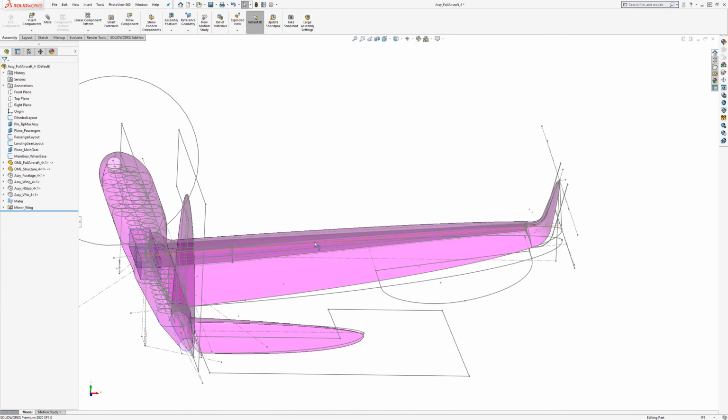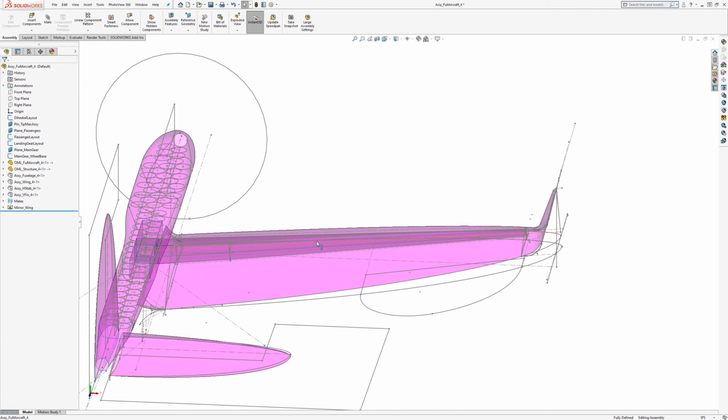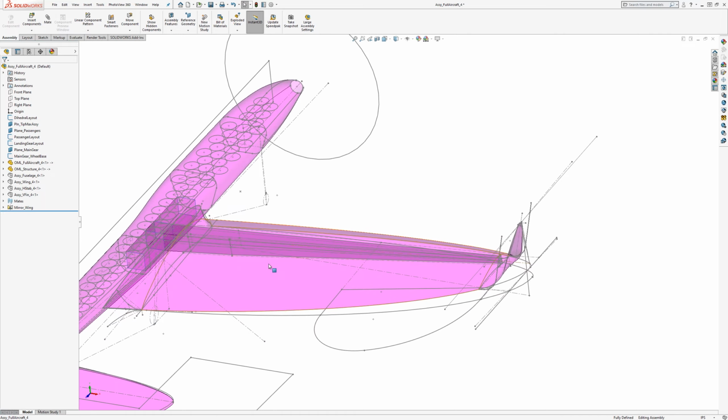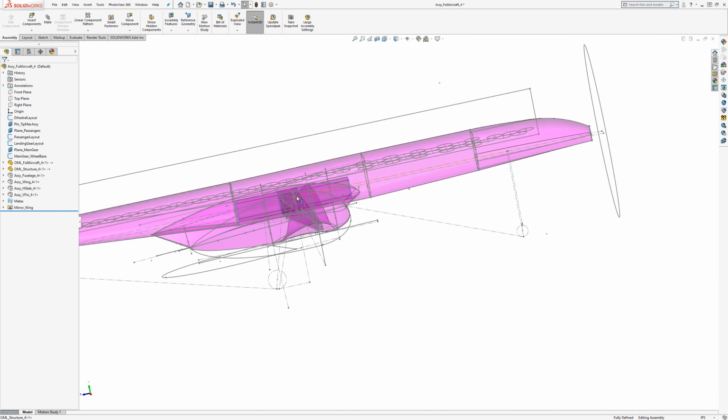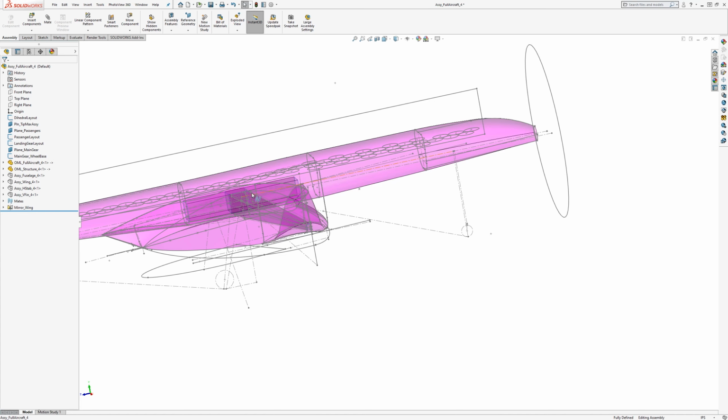It's taking that information to help design a beam, sort of the outer surface of a beam, to reference later on for the actual parts that will make up that wing box. And here, I was going for a beam that filled up close to as much depth as it could in the deepest part of the wing, so from maybe like 20% chord back to like 40 or something like that.